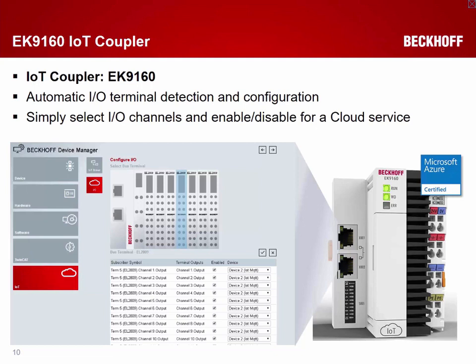And of course, this also goes the other way around. So you can also subscribe to data. If you have output terminals, like digital output terminals, you can also subscribe them to a message broker and then send commands to the EK9160 via the message broker, and then the output terminals are being switched on or off depending on the message that comes in.